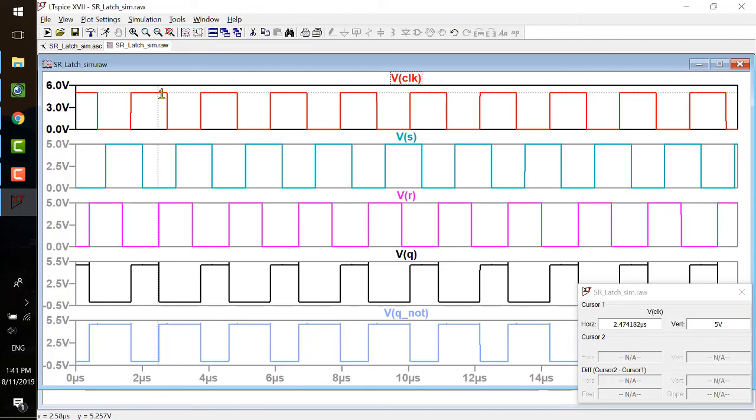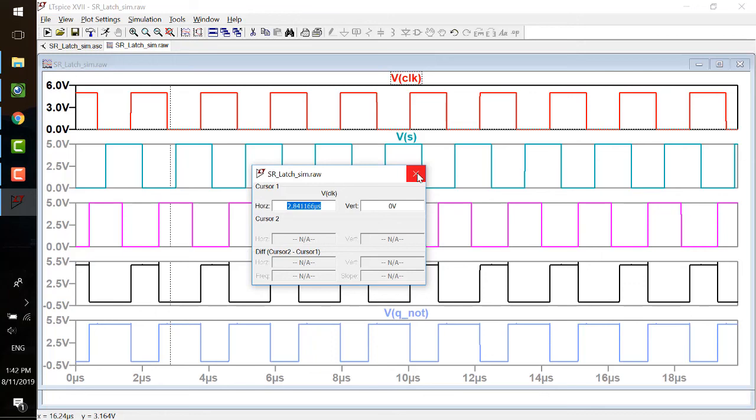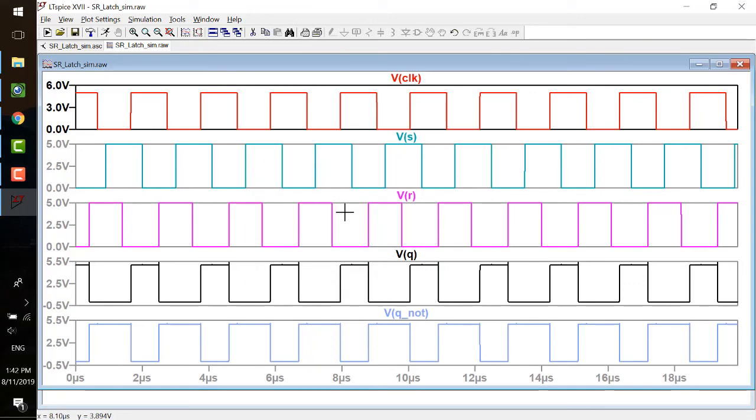And here you have a status change because clock is still 1, so it's invalid, but you have your S and R signals swapped. So now it's trying to reset the signal, and you are getting a 0 here, okay? You can do it so on and so forth. It's going to work for all these signals. This is really the way I can think of to verify your flip-flop. It's kind of like in sequence, which makes this a little bit difficult compared to the combinational logic.